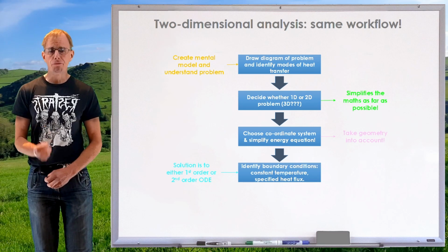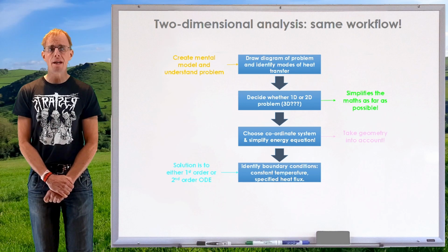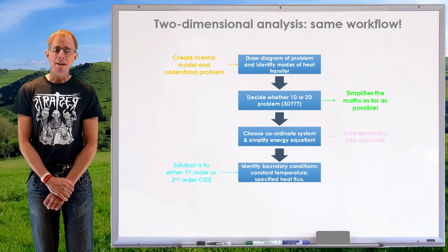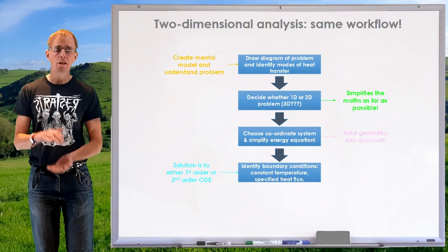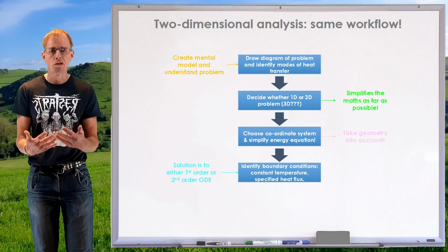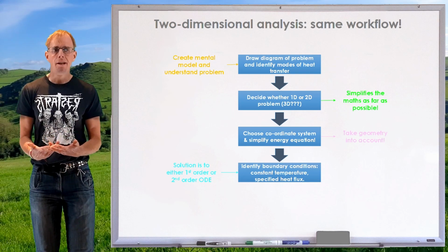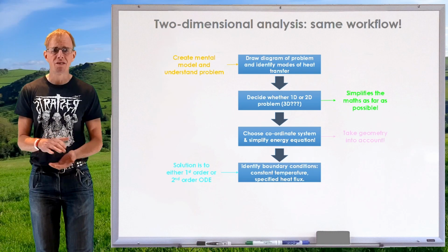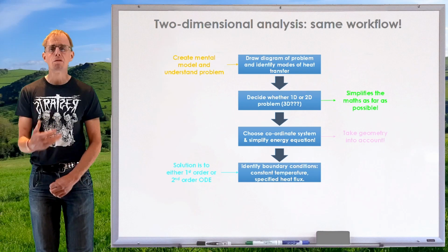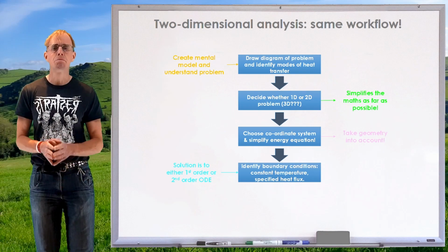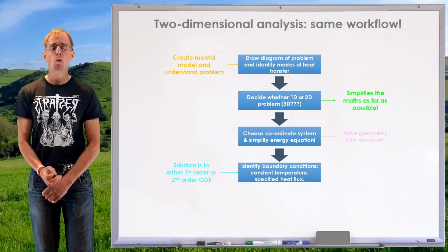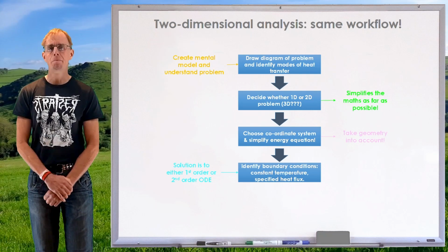If convection dominates the problem, then, conversely, if we've got a poor conductor, we're probably going to be generating an internal temperature profile because as heat leaves the surface, more heat's got to replenish that surface from the interior of the material. And if we've got a poor conductor, that's actually going to be the rate limiting step in the problem. So we can invoke a non-dimensional group in step 2 to help us understand the problem yet further. Step 3 is we chose the coordinate system that best represented the problem.